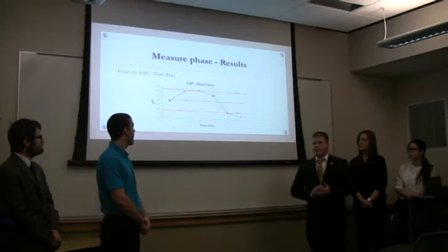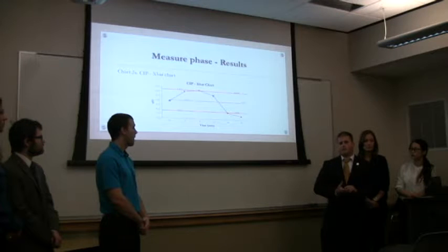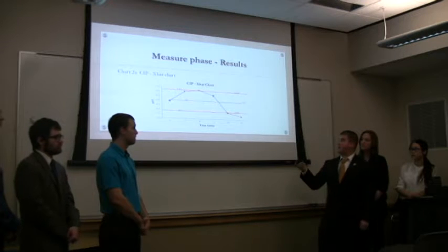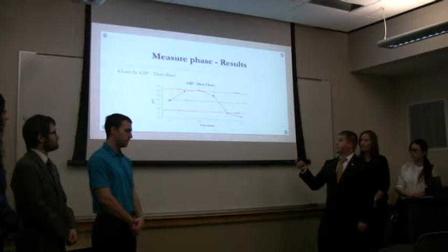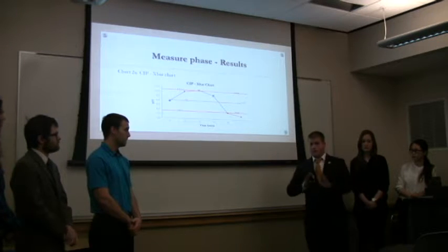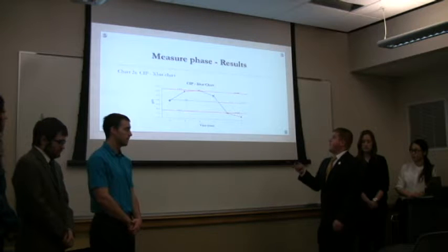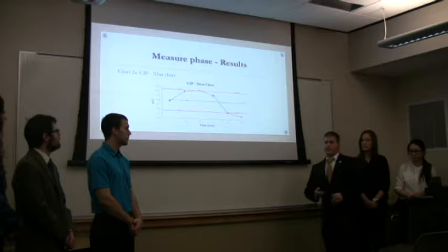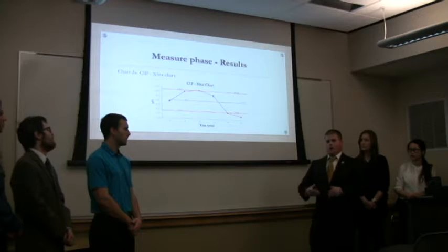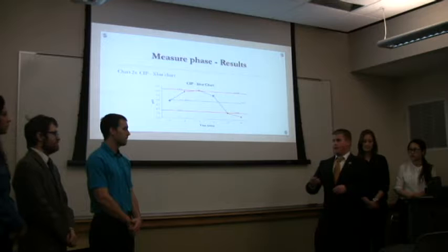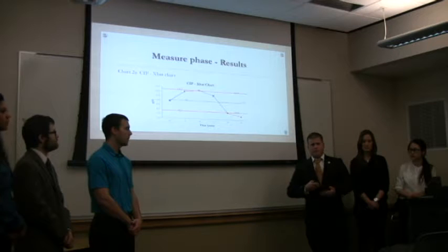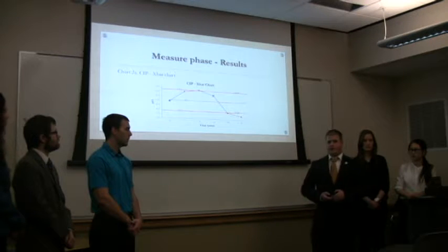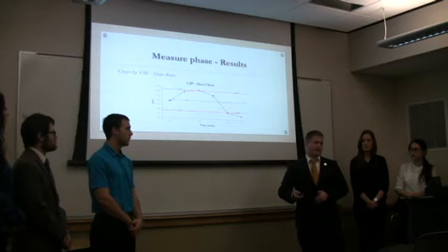Now, we decided to use an X-bar chart. The usefulness of X-bar charts is they allow us to see the distribution of average mean data over a span of limits that we decide based off of a center line average. So our center line is the grand total average of everything, all the samples put together as one. And then these control limits, the lower and upper, are a calculation of plus or minus the correction value multiplied by the average range. The correction value is just a simple factor created in statistics to account for error, either in range or standard deviation with a varying subgroup.